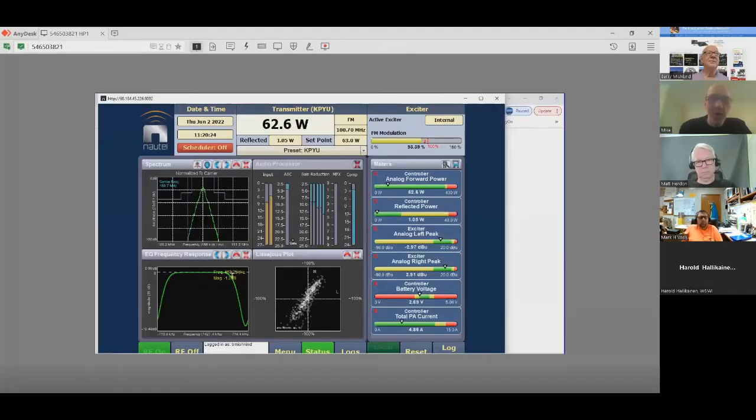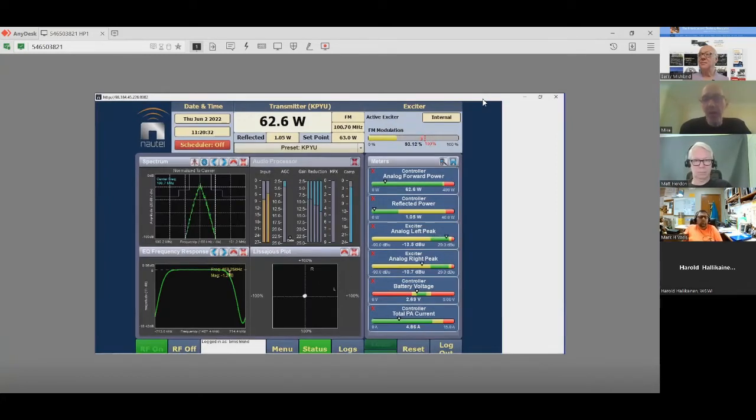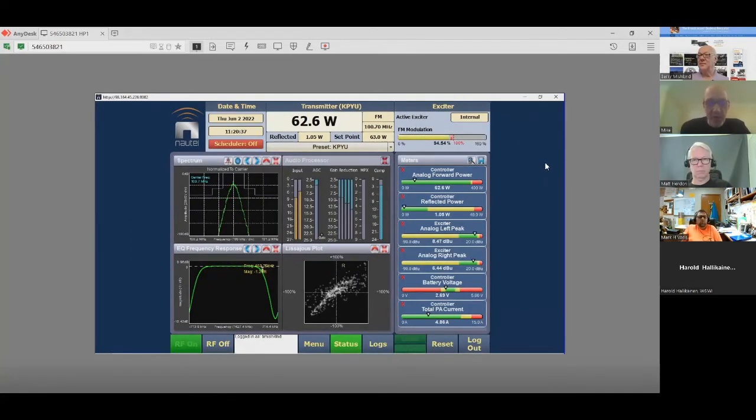We can typically compensate for the high Q nature of a channel combiner that might have undesirable group delay or amplitude versus frequency response issues. So we can put in a filter to compensate for unwanted transmission line linear distortions.